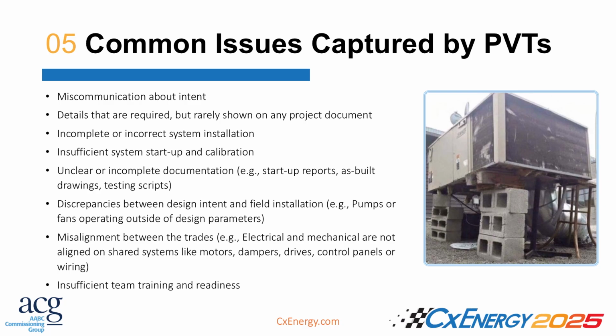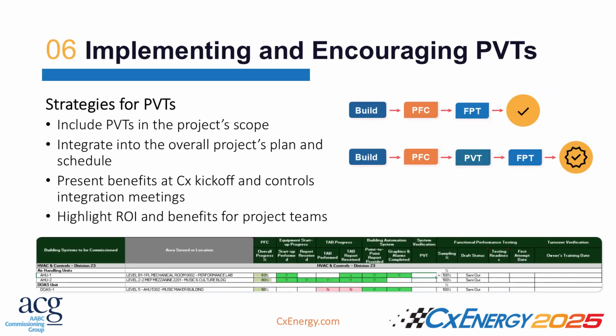So what you need to do is you need to have a conversation. Well, first of all, depending on the owner, the owner may have a requirement to conduct pre-verification testing, and then it's simple because it would probably be in the OPR document, which would state the requirements for the pre-verification testing, for the functional testing. And if it does not, again, you just want to make sure it's in the spec.